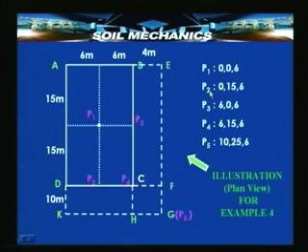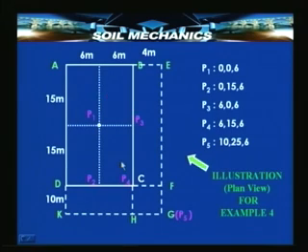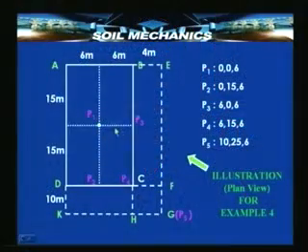So, these are the points P1, P2, P3, P4, P5 at which we want the stresses. So, now what we need to do is to successively put these points below the corner of a rectangle and calculate the influence coefficient and then compute the vertical stress. For example, if I take P1, if I consider these 4 small rectangles which meet at this point P1, I can say that P1 is already at the corner of 4 different rectangles. So, if I can calculate the influence factor for one rectangle and the corresponding stress,